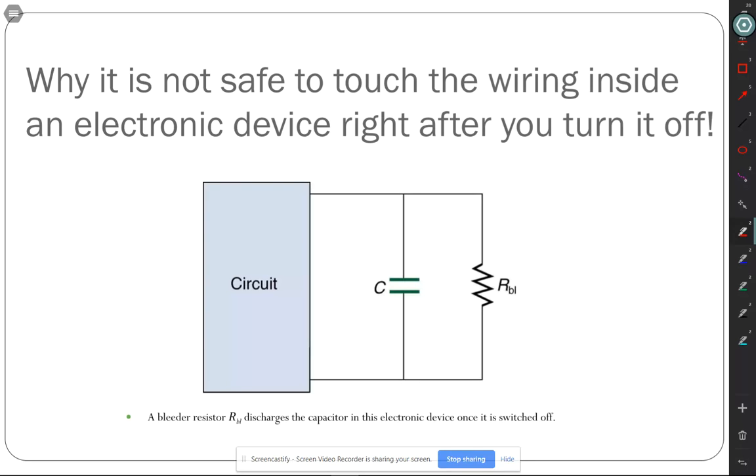We also pull the diaphragm, sing with your diaphragm. So we push the air out of our lungs. Well, if you've got that current going across your chest, what happens is you suffocate because you can't breathe. Because you just pushed everything out and you can't let anything back in. So one of the first risks with electricity is suffocation, which is pretty much not the way you want to go, right? You're shaking about and you can't breathe. You don't want that. So that's the first real deadly thing.